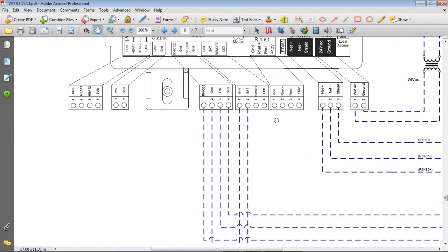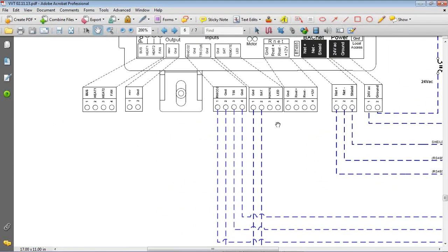But moving on here, the next plug, this is where you'd wire your supply air temperature sensor into inputs 1 and 2. You need a supply air sensor in order for one of these to function. It's important because it needs to know what type of air is coming to the damper, and based on that, it knows how to regulate the air to the space. So if you have cold air coming and your zone needs heat, that zone damper is going to close, and vice versa. So you need a supply air temperature sensor.